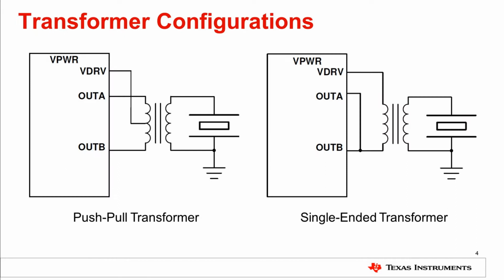In a transformer driver, the IC provides burst generation by exciting the primary side of a push-pull or single-ended transformer. A DC voltage can be tied to the center tap or high side of the transformer. The objective of the transformer driver is to convert a small DC voltage to a large sinusoidal voltage at the transducer. Many transducers require a driver voltage of up to several hundreds volts peak to peak to maximize the amount